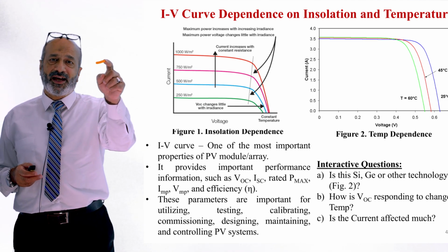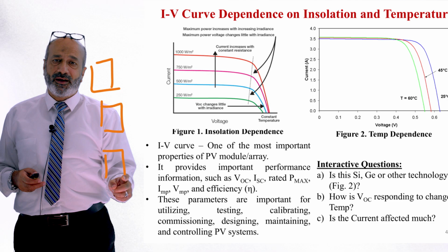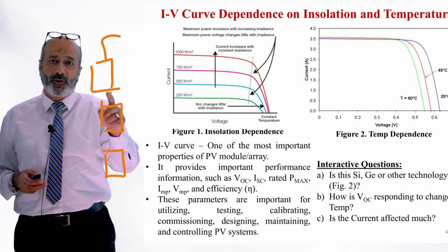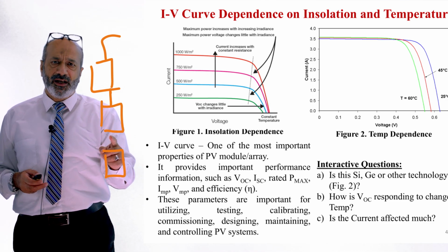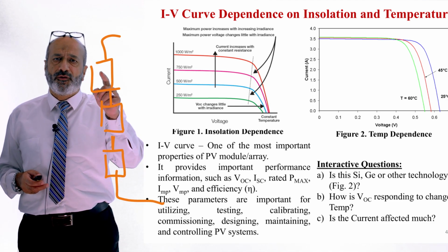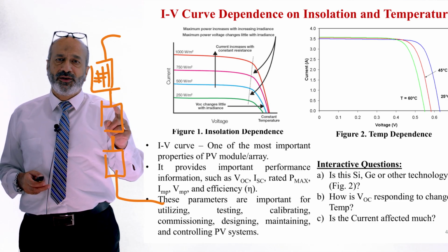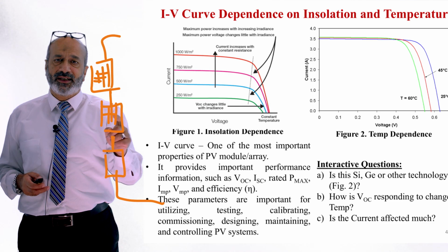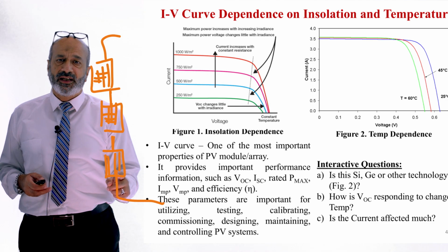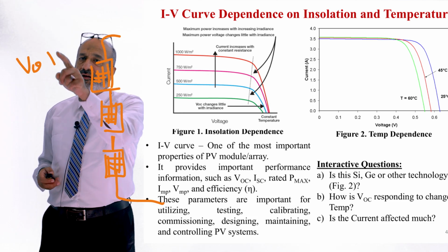Module means the arrangement of series and parallel connections of those cells, forming, as you can see here in the drawing, the PV panel. Why do we connect those cells in series and parallel? To receive the desired voltage and current.